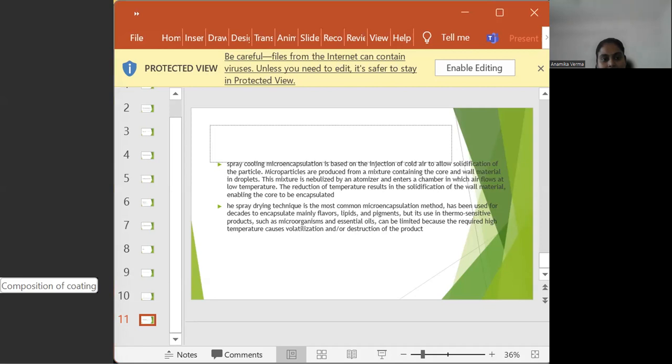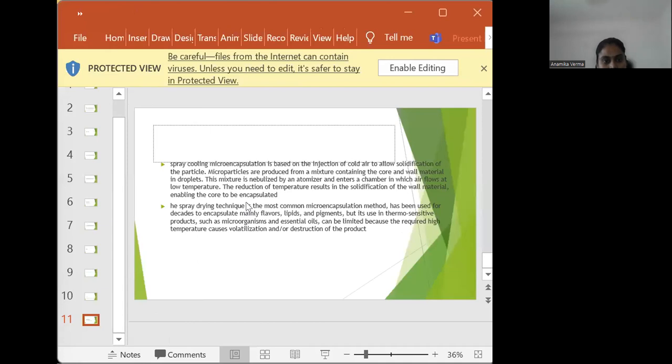In a spray drying method, the coating solidification is effected by the quick evaporation of a solvent in which the coating material is dissolved. In a spray congealing method, the coating solidification is accomplished by the thermal congealing of the molten coating material, or by solidifying a dissolved coating by introducing the coating core material mixture into a non-solvent. Removal of the non-solvent from the coated product is often done by sorption, extraction, or evaporation.